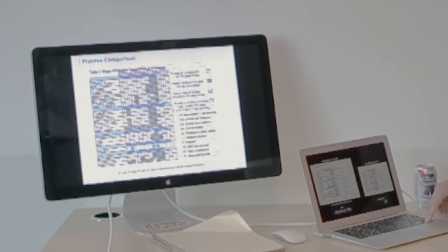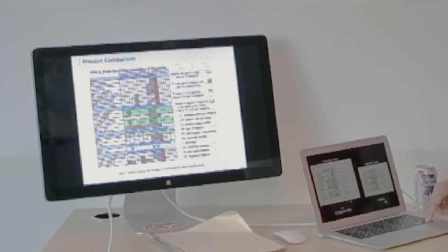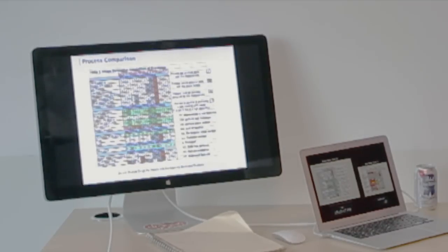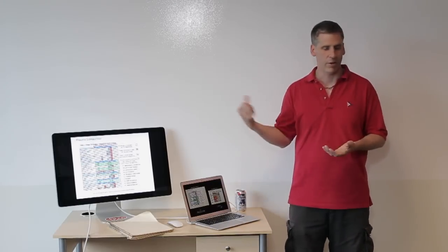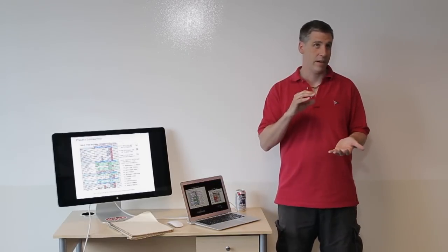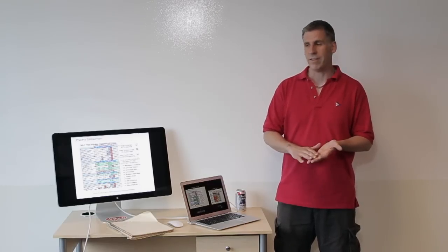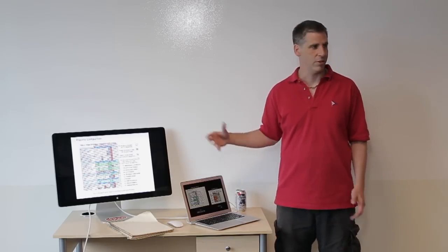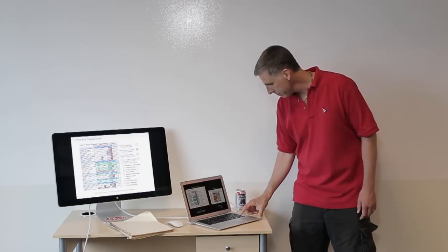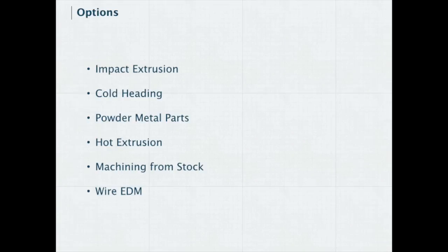So what you could do is overlay the last chart up here where we went through all the different options, and then for these 6, pick which materials would be applicable. And that's where you'd factor in the environmental considerations. So on the part slide, we said we wanted it to operate up to 500 degrees Fahrenheit, let's say, and survive in a bath of light acids and bases. So you may find some materials aren't conducive to that, and then you disqualify those. So based on that, these are our 6 different options.